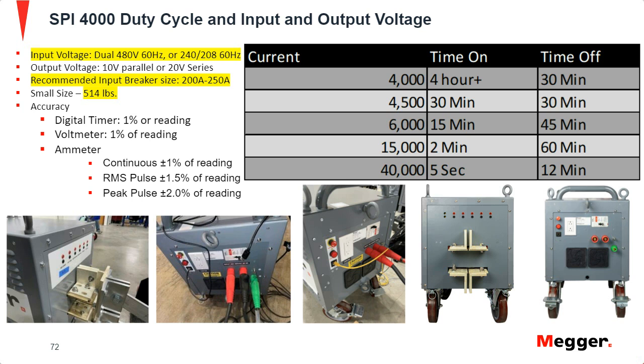But if it's a critical application, of course, we would recommend to at least test the high amperage low voltage breakers, around 1000 amps or more. If your institution or organization wants you to test all the breakers, you would have to test all the breakers in the MCC panels. But there are no specific guidelines on the sizing of breakers related to MCC, on what type of breakers we should conduct the testing on. But if it's a critical application, definitely we would recommend that.